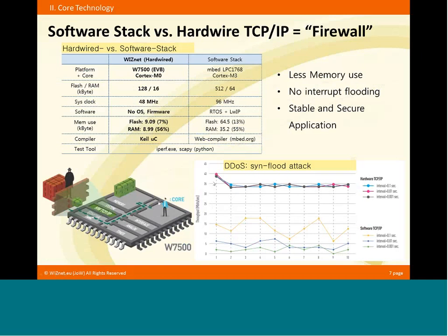That's why we have here this 35 megabits of data throughput. And this is even not using direct memory access. We have a DMA engine here, so we can even increase the speed a little bit. Or let's say we can reduce the core load on processing data from memory to TCP/IP.